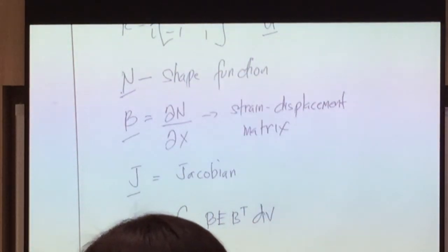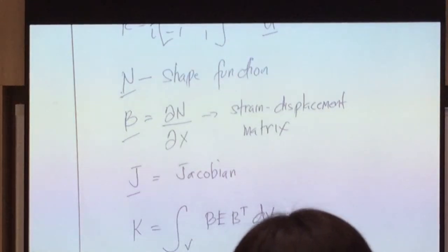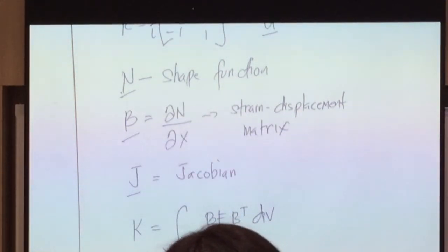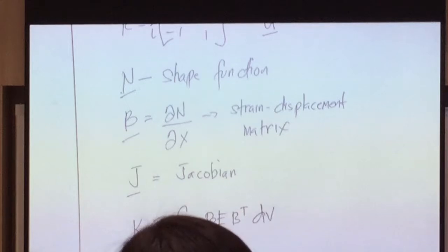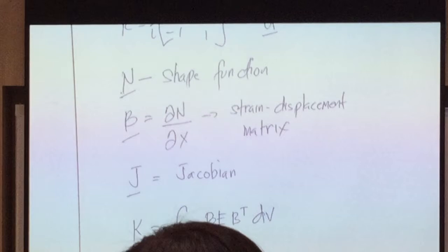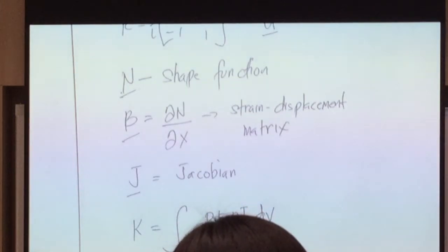What's the symbolic representation? This one is your symbolic representation for stiffness for a bar. You probably have seen the beam already, as well as the frame. So what I'm saying is that we cannot get a similar representation for 2D elements. We can just put numbers there. To be able to get the numbers, you have to perform integration. Not analytical integration, but numerical integration, which is rather straightforward, like I said.